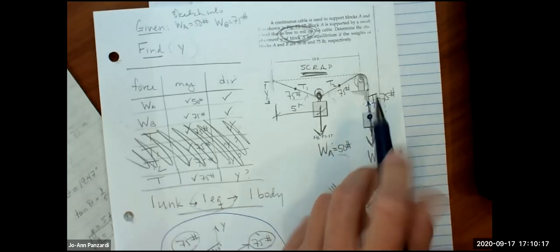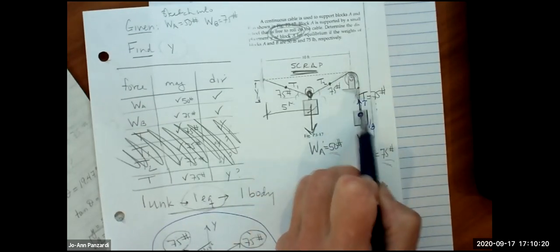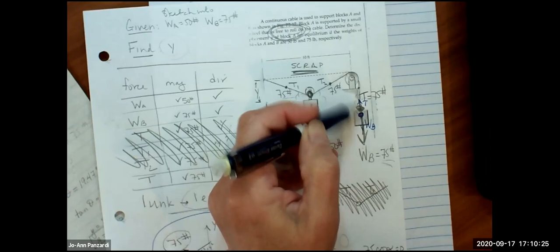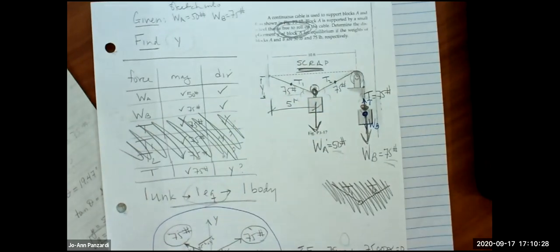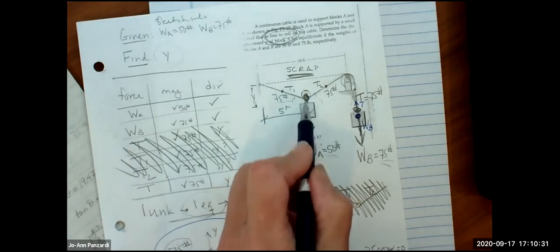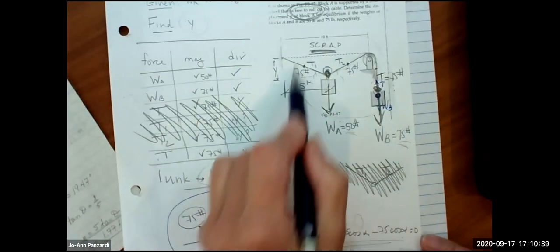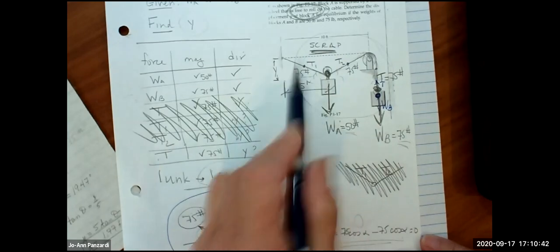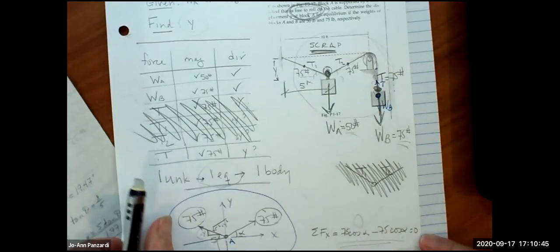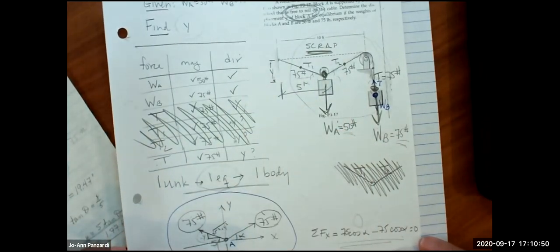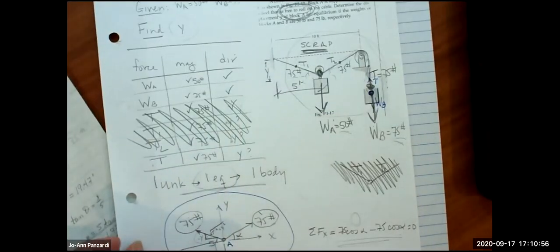Well, right now we're doing statics of particles problems, right? If we pick this point right here to do our free body diagram of, the only equation we have is sum of the forces in the Y. Right? And we're always choosing a point where all the forces are, including the unknown. That makes sense, right? So we're not doing a free body diagram of the whole thing, because then we would have to do some of the moments, and we're not doing moments yet. So you want to pick the point where all the forces converge. Does that make sense, Angel? You wouldn't want to do it over here because it wouldn't help you.